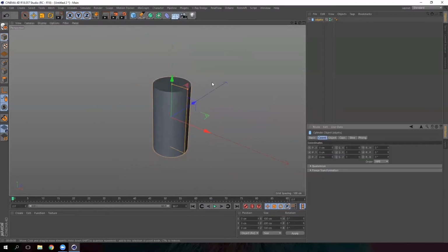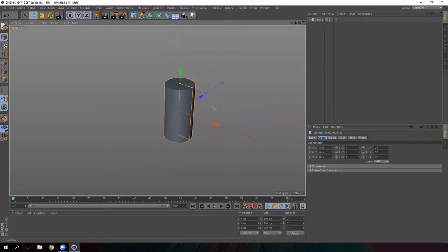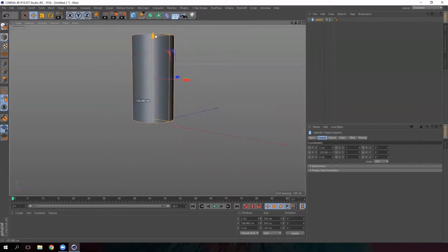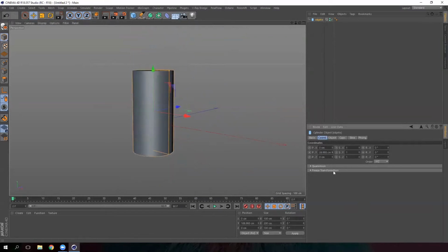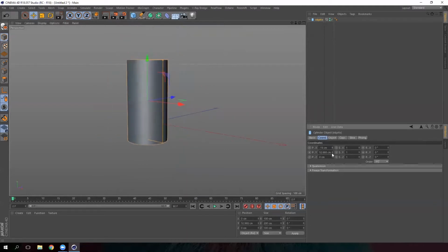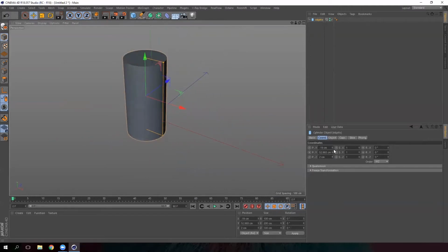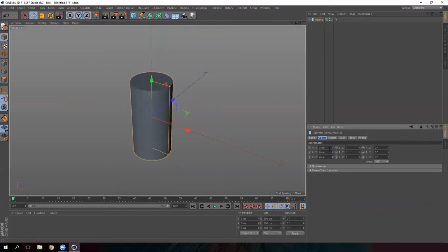The next options will be coordinates, scales, and rotation. Here we're going to change the axis. So, if we want to move the object, you can simply do it with the options we have here. And here we'll see how many centimeters it has moved in every axis: X, Y, and Z. Great! If we right-click on the button tab, we reset the object. That is 0 position.